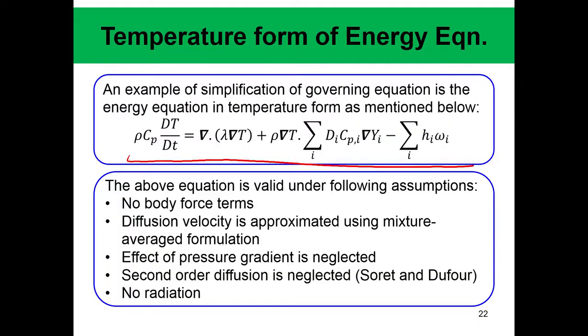This is how you actually solve the energy equation in a CFD code or when you are analytically computing some flames. And this is an example of simplification. It involves some more simplifications though, with some assumptions as will come later. But this is the equation, that is rho Cp times the total derivative of temperature, which is essentially this diffusion term, the heat conduction term, plus of course this one, which arises due to the different Cp_i's, and then the heat release rate term.